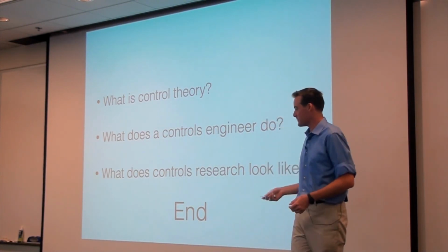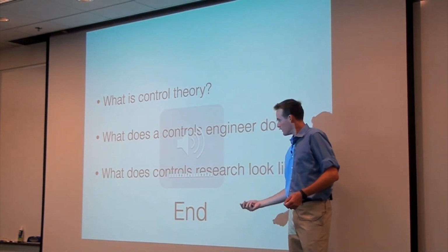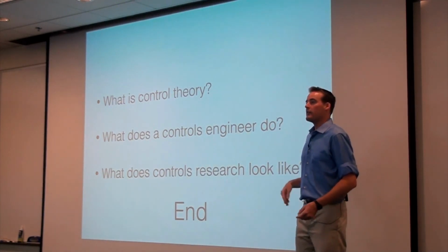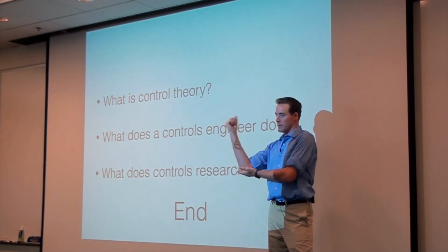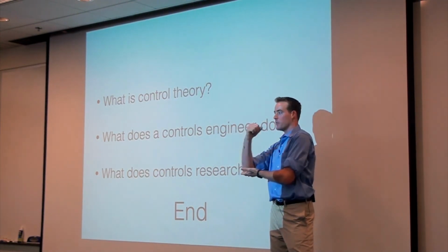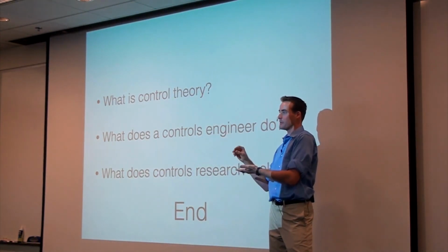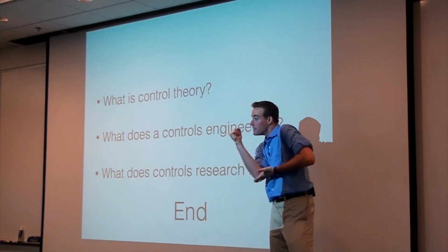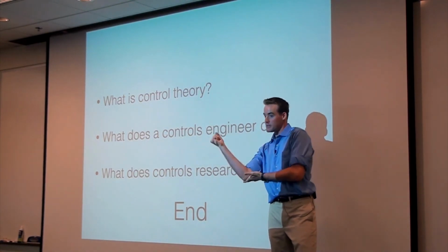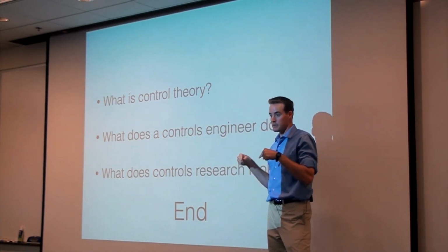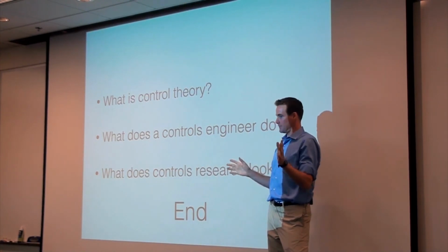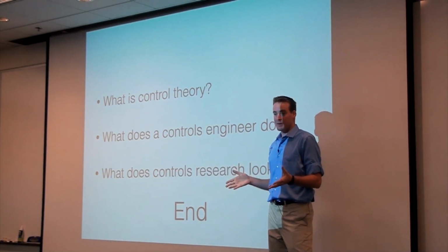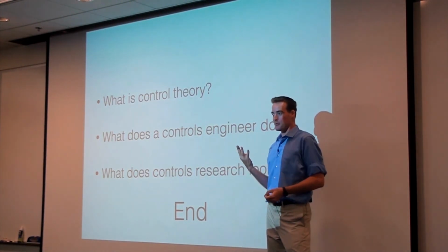Stephen is very cleverly pointing out that there are only two measurements of the inverted pendulum. We know where the cart is because we have a wheel encoder, and we know the angle of the pendulum because we have another encoder. We are not measuring the other two states, the velocity of the cart and the angular velocity of the pendulum. We don't have sensors directly measuring those things. So, I glossed over this in the interest of time, you cannot directly use state feedback because you just don't have all of those four things being measured.